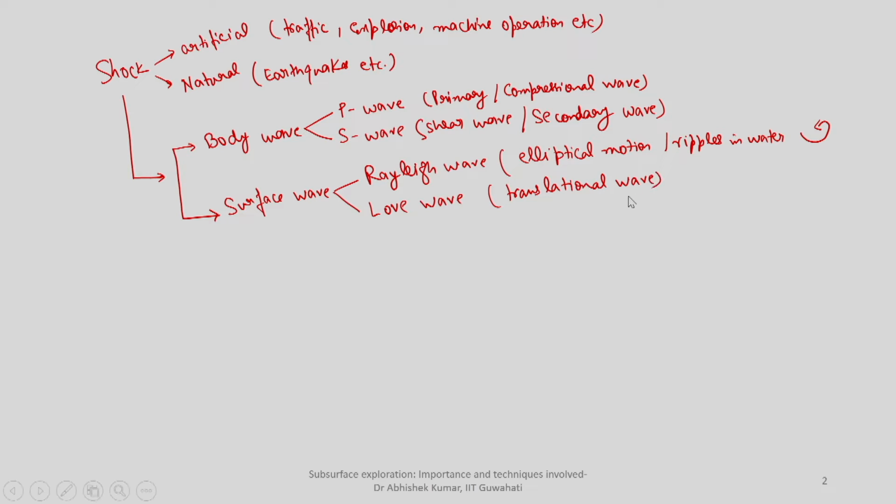When we discussed the seismic reflection method, we focused more on primary waves, that is P wave interpretation, and then, based on the Poisson's ratio of the material through which the waves are passing, once you know the P wave velocity, you can classify the material and also determine the shear wave velocity.